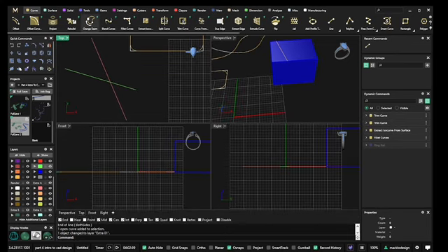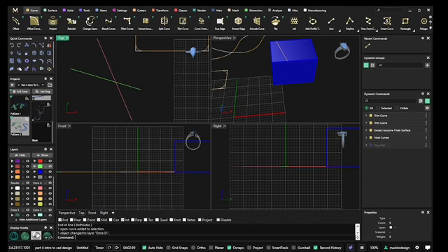And then we are going to come up right below the viewport and make sure that our intersection, yes, our intersection is on. I'm going to click off center because we don't need that, and I'm going to click off quad, but the intersection is on, and I always leave mid and end on.